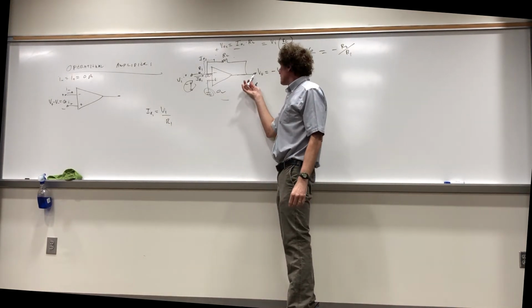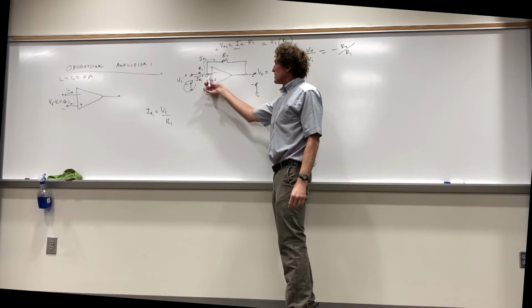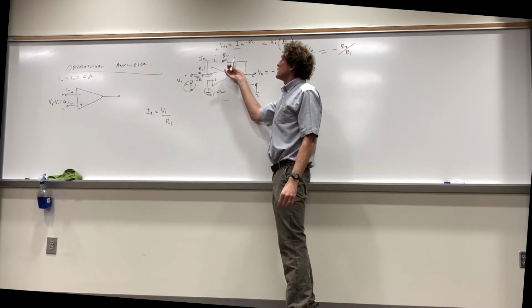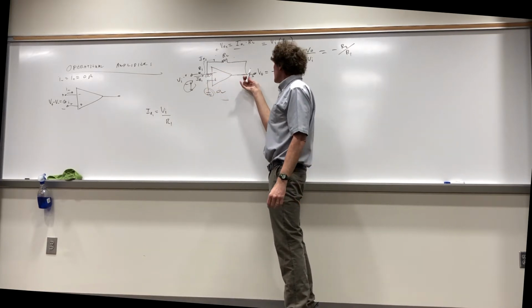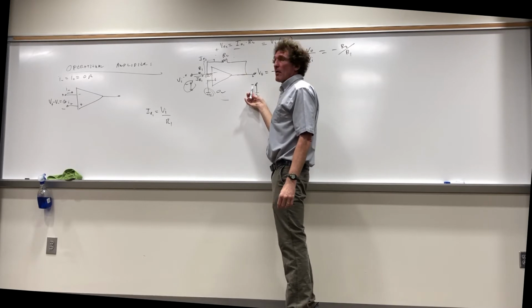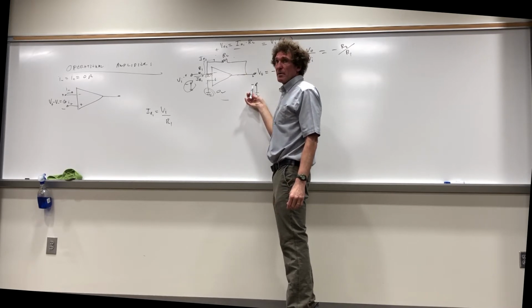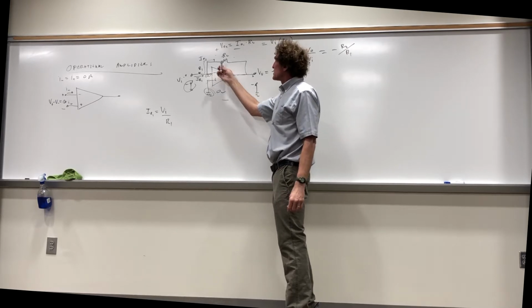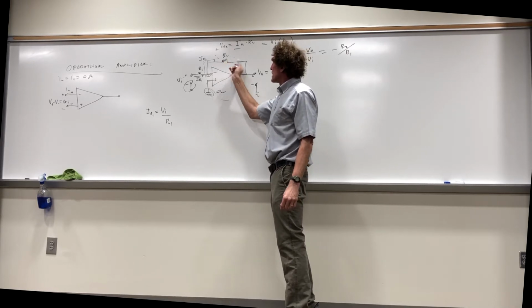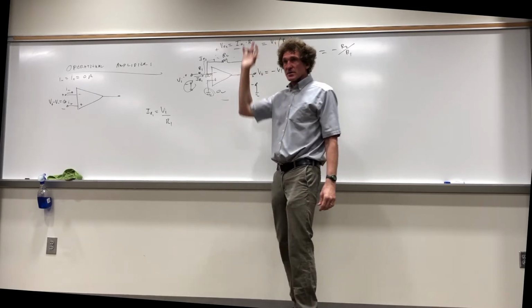You remember, you want the voltage from here to here. It would be no difference here. This would be a voltage drop, minus VR2, and then it would be plus V out equals 0, right? Or V out would be minus VR2. Okay, so you're going into the op amp. Sir, this is a voltage drop, right? It's plus to minus, correct? How many see this right?